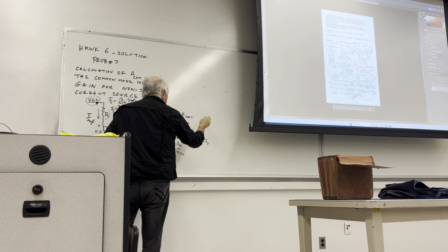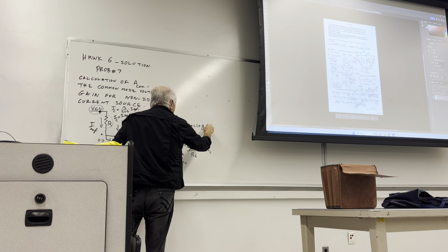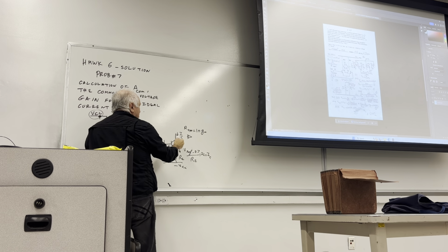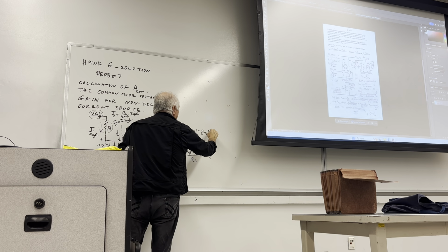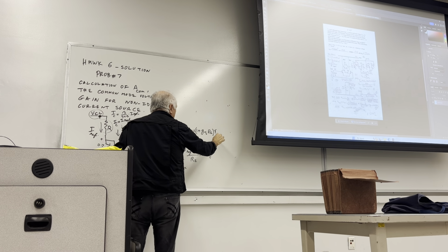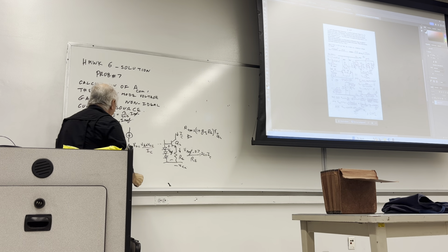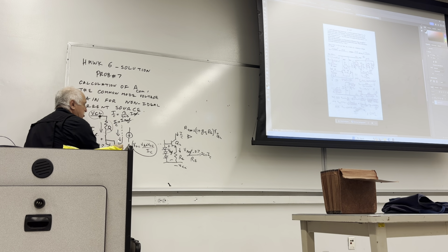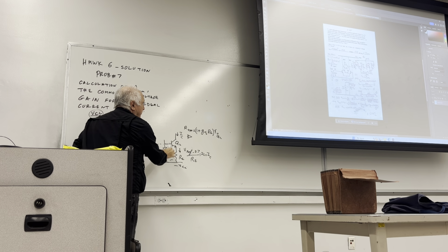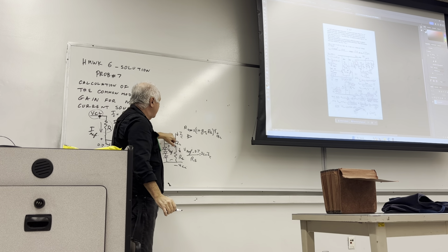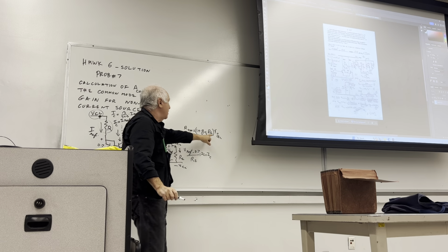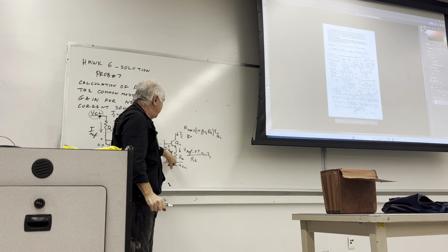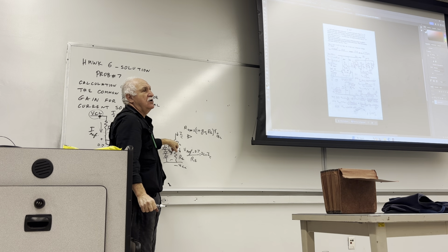The dynamic resistance will be equal to 1 plus Gm of, let's call that transistor Q2, Gm of the Q2 multiplied by Re multiplied by the Ro of the Q2. So what we used to have in here, which was just the Ro of one single transistor, in this format, the dynamic resistance between the collector and the reference ground will be way, way higher because it will multiply by the influence of that resistance and the Gm of that circuit.